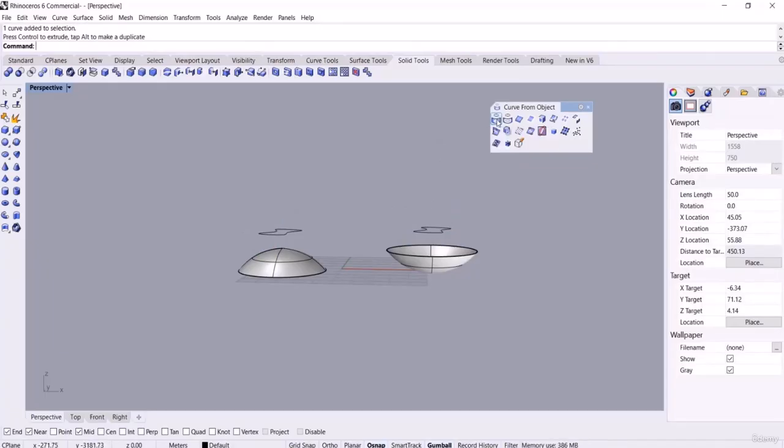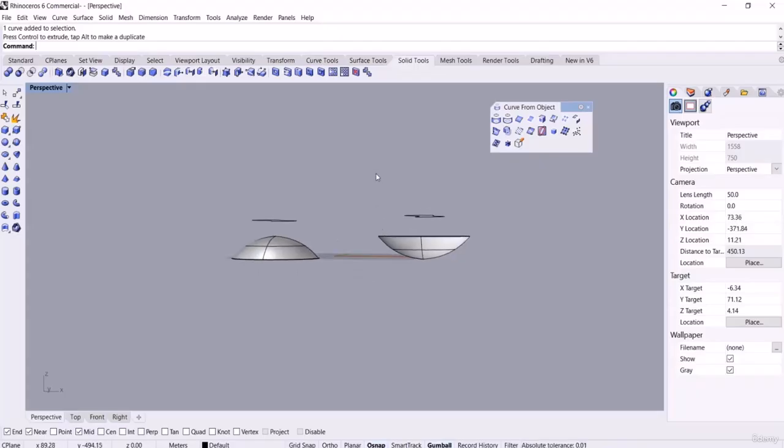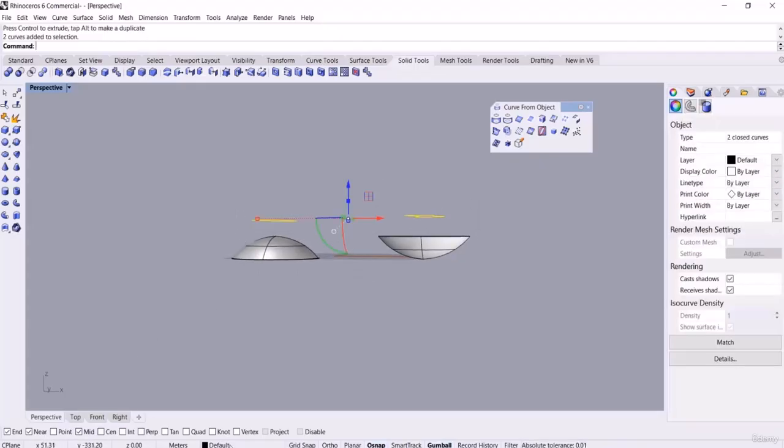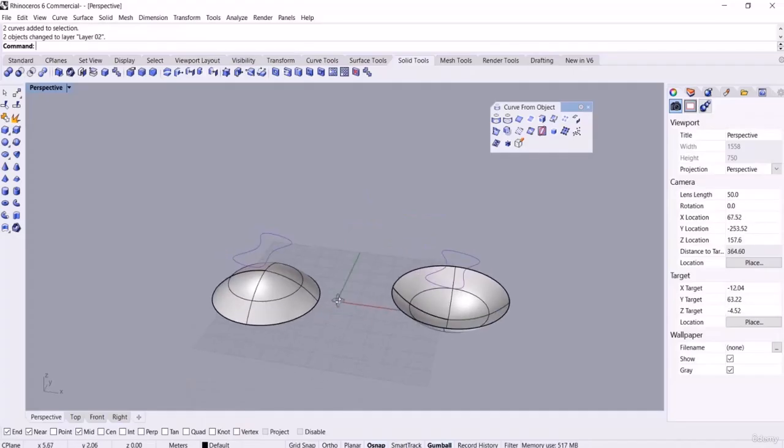Project curves creates curves or points on a surface that are the intersections of the surface and curves or points projected toward the construction plane. In the continuation, let us consider the function. I modify the layers so that you can compare the curve with the projected curve. Let's see. When we start project curves, it projected the curves on the specified surface perpendicular to the construction plane